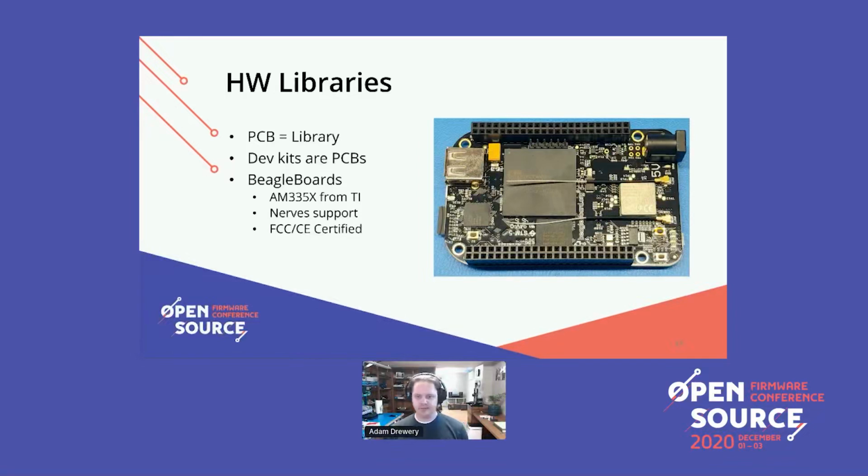So a dev kit will provide you the access, and again, at the risk of stating something obvious, the dev kit is a PCB, and it will allow you the access to the majority of the microcontroller functionality. We at Very are particularly fond of the BeagleBone series of single board computers. They are built on the AM335X from TI. They're a good general purpose industrial microcontroller. Most importantly, they have Nerves support.